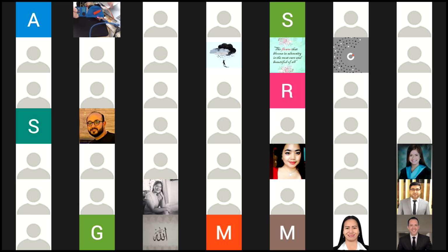So here, what you can see is the servo motor with the indicator of the temperature. We have a temperature and humidity sensor, a buzzer, and a LED. I want to heat my humidity and temperature sensor in order to create a LED light and a sound from the buzzer if the temperature is higher than 30 degrees.